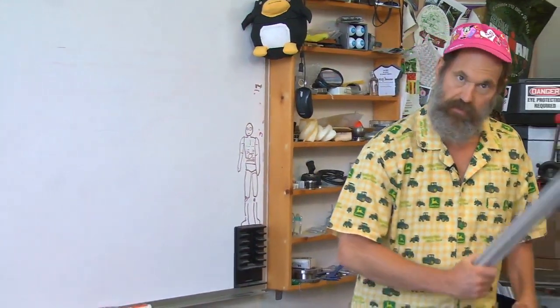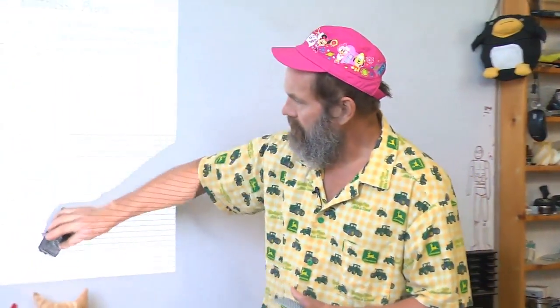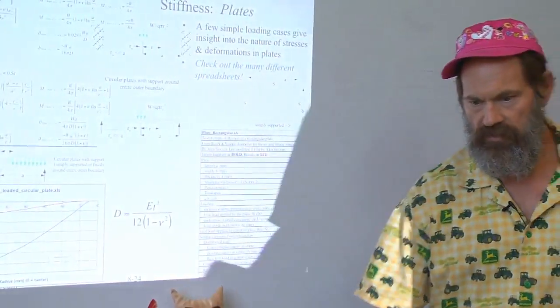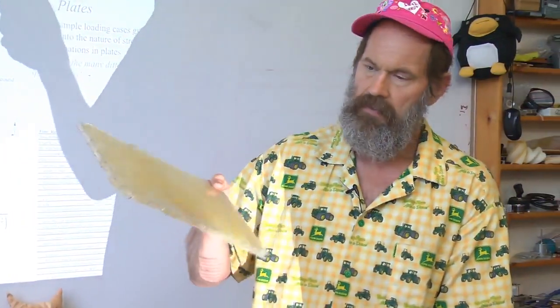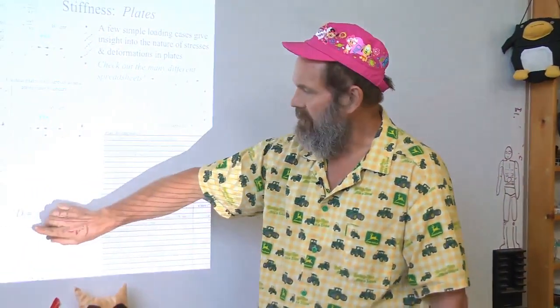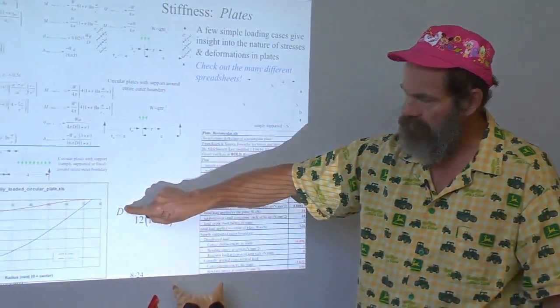Now, most machines are not designed as just blocks with some stuff removed. Remember, most machines are constructed of beams and plates. Closing the loop through the plate is very important, as we showed with these different structures here. These started out as plates, and with these structures we added features to them to stiffen them up, to make them thicker by giving us an effective deeper depth.